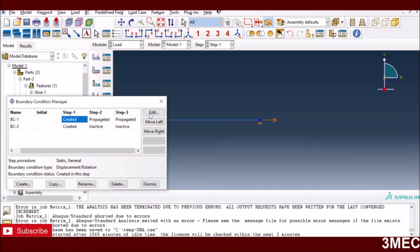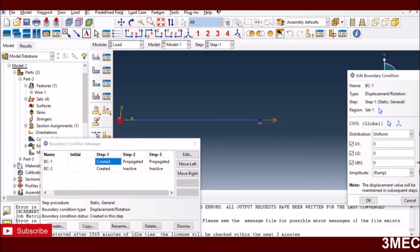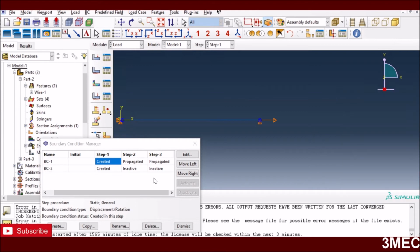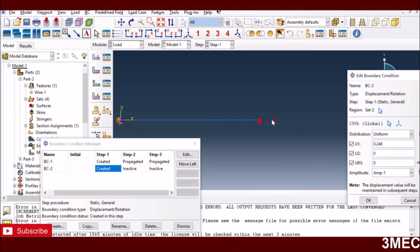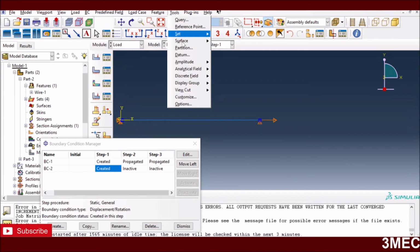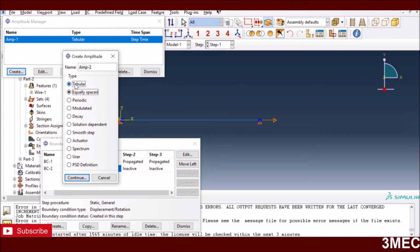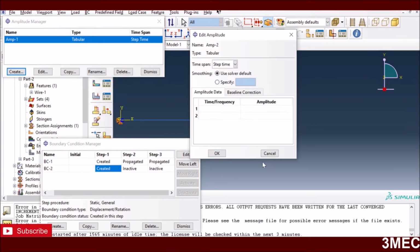So they had fixed ends, because this is the one end of the matrix material, this is the other end of the matrix material. So I have fixed everything from one side, while on the other side I only let it move in the horizontal direction with the displacement of this, while I'm using an amplitude of amp1. And what is this amplitude? Again, you can create amplitude directly there, or you can create it from here. So you can create an amplitude, choose tabular, and then you can give the values here.